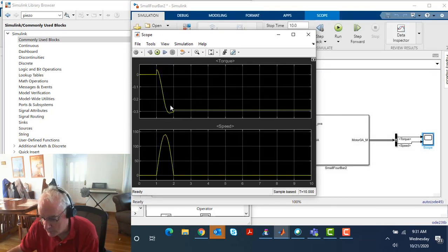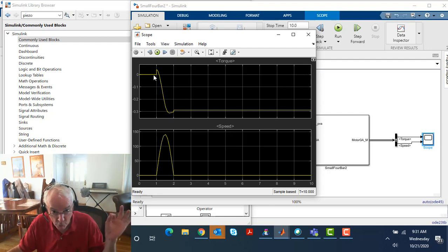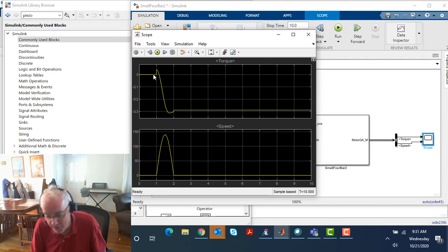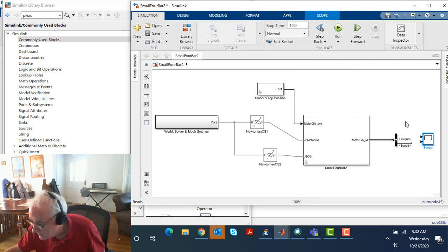So our top figure is torque. We see its maximum, and I think this is very important. It's an absolute value because measurement of torque in general is dependent on what your reference frame is. So plus or negative is a somewhat arbitrary characteristic based on how you chose to make that measurement. But anyways, the maximum value is about 0.3 Newton meters, and the maximum velocity is, in degrees, about 170 degrees per second. And I think this is a relevant point.